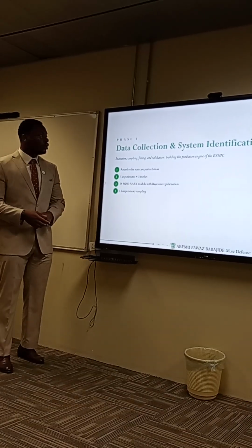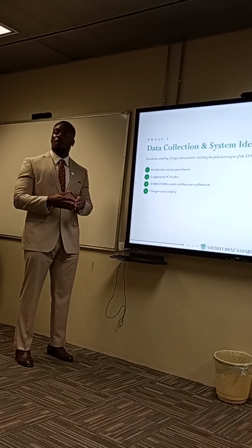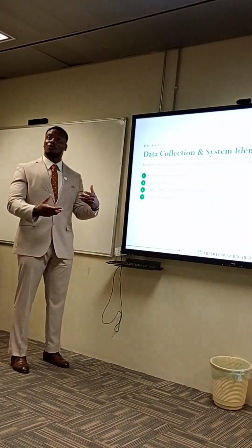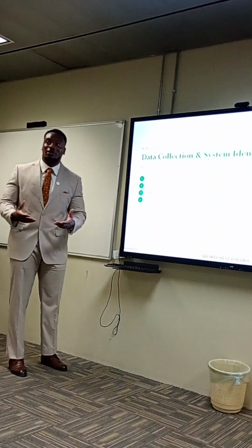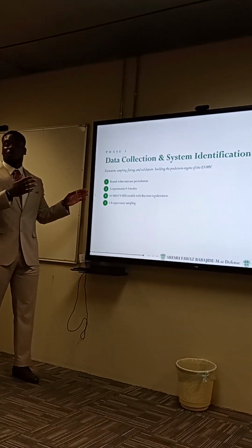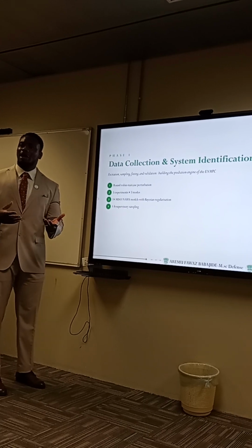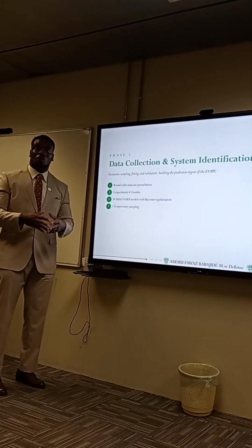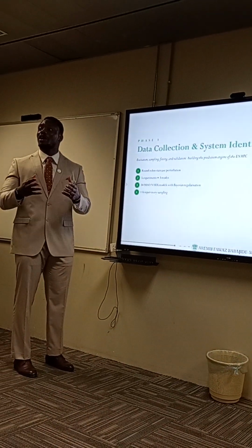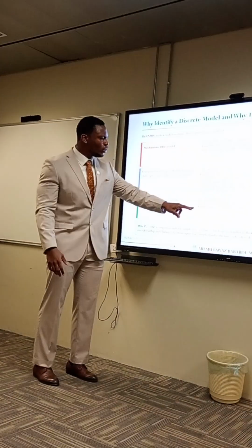So we start with phase 1, data collection and system identification. This is a very integral and major part of this thesis. Data collection is a skill, because in industry you're never allowed to perturb more than 5%. So it's a very handy tool, especially when it comes to getting data from the plant and identifying a model. Everybody in control engineering will agree with me that identifying a model that really captures the dynamics of your process is a very tedious job, and it has to be done with good precision.